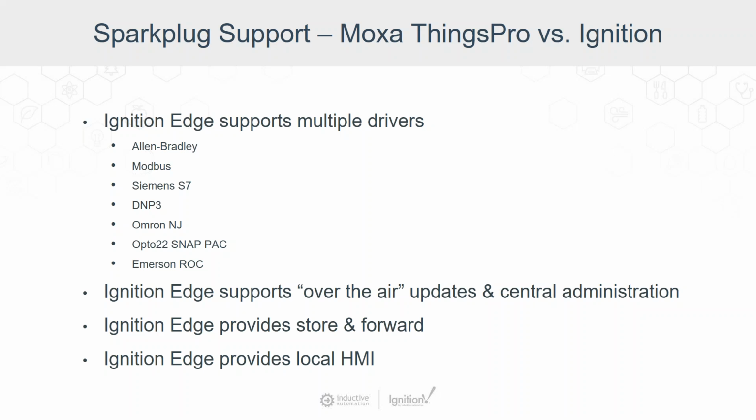One note that I want to mention here about MQTT is that Moxa's equipment, actually with Things Pro, supports MQTT Sparkplug natively, and they have a Modbus driver there, and a lot of these different equipments will support Sparkplug natively. If it's a PLC or sensor that supports MQTT, perfect, because then there's no need for any edge gateways like Ignition to poll and to do those protocol conversions. It already supports it at the edge of the network. But then there are these different polling protocols, and sometimes the equipment will be able to communicate to that PLC directly, poll it, and publish through MQTT. And Things Pro does that for Modbus in particular.